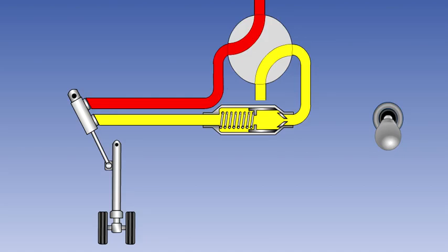If it was placed on the inlet side of the actuator, whose speed is being controlled, it would cause a pressure drop in the cylinder, leading to cavitation. This could cause damage to the actuator. You can operate the switch with your mouse to observe the operation of the restrictor valve as the gear moves up and down.